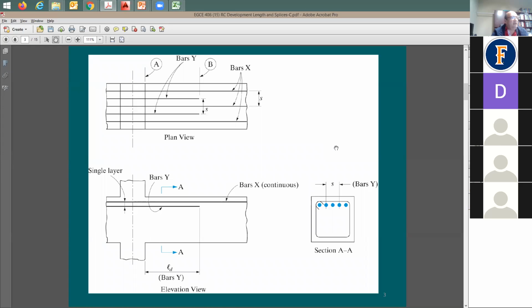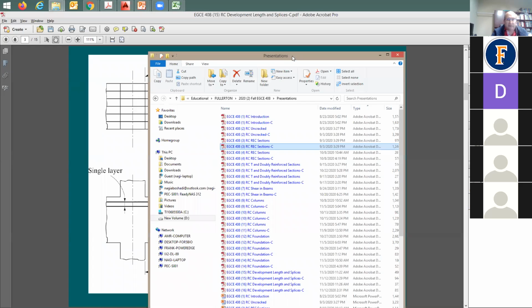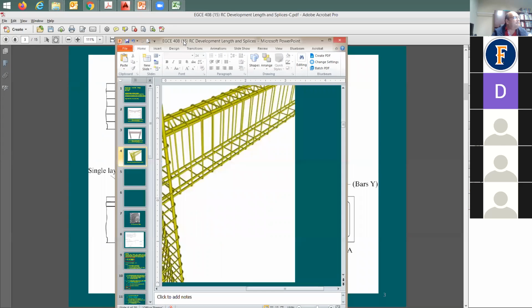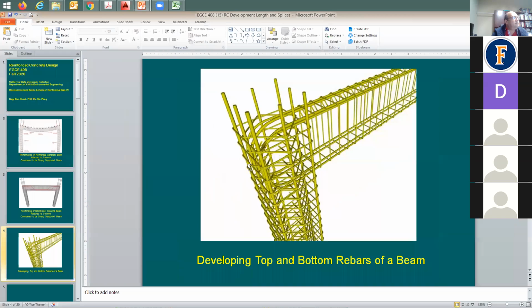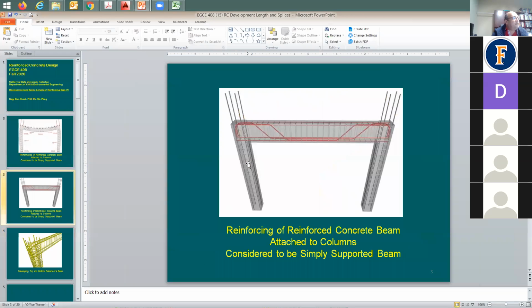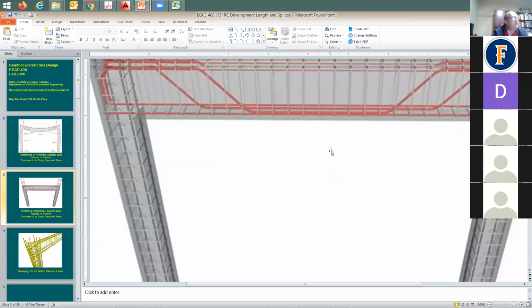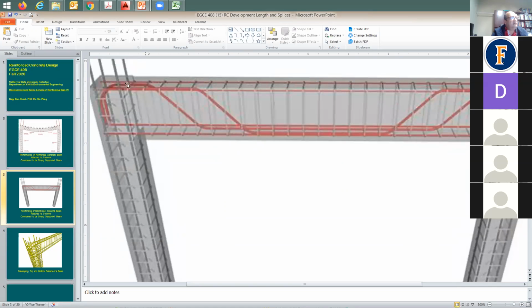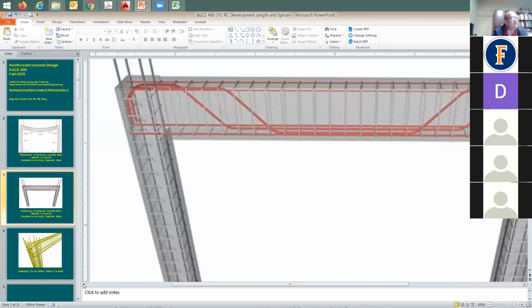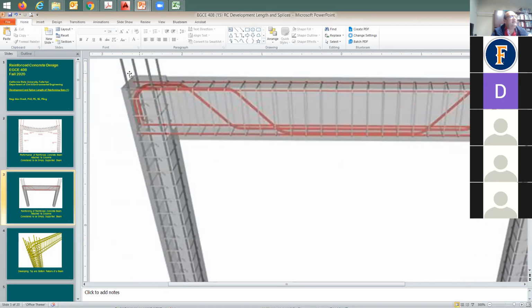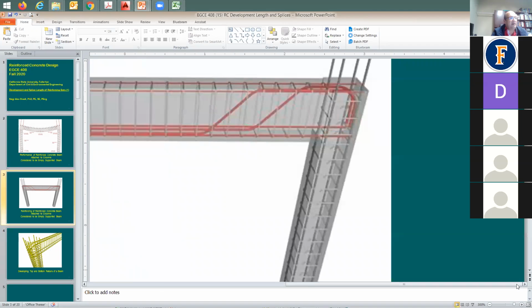Okay, now I'm looking here at a detail. Here's a column and here's a beam, and I'm trying to discuss this issue. Let me put this back. I said this rebar, the top rebar, just stops here. But let's say I have another beam on the left side of this. I'd like now to extend the rebar from here, and same thing, I have another beam from this side. So I'm going to be extending the top bar in the other beam span, if you like.